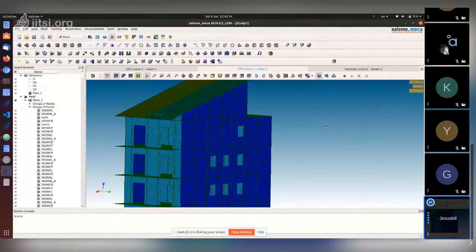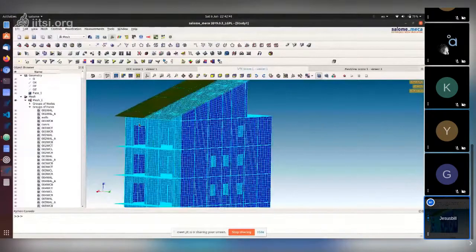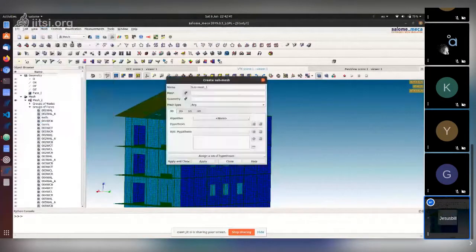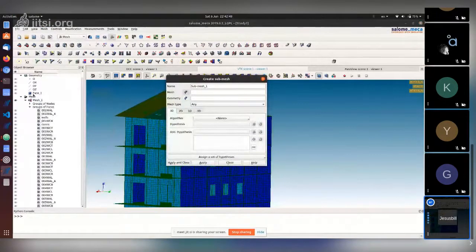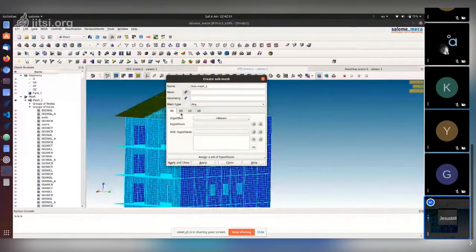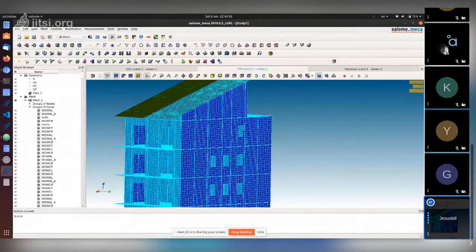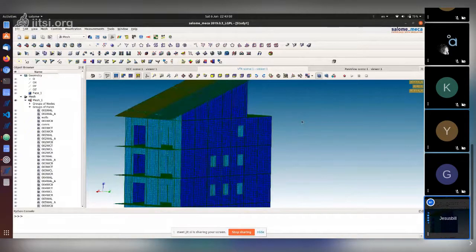I prefer to have a good procedure so that I do the mesh and that's it. You can have sub-meshes, so you can select some geometries and tell it how you want them meshed. So in the end, you have a lot of flexibility to select groups that you want with a certain type of mesh. And then it also depends how you set up your geometry.